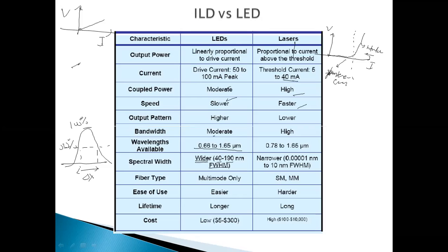For the fiber type, as I mentioned before, LEDs can only be used with multi-mode fiber, but lasers can be used with both single mode and multi-mode. The LEDs are easier to use, while lasers are a bit harder, but not very complicated.